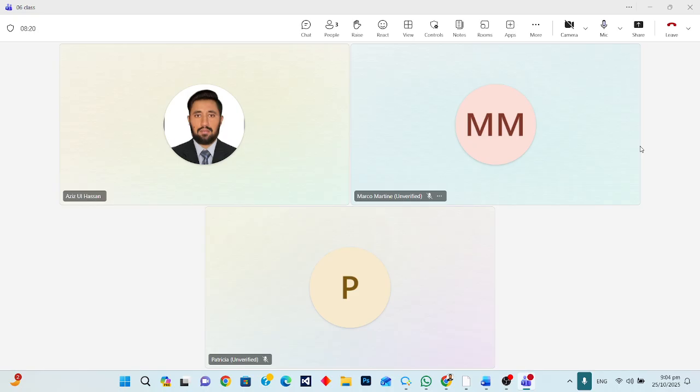For that calculation, we need to apply the classes of the LPS protection through the rolling sphere method in the PV area. So when we perform this risk assessment as per the IEC standard and the lightning protection as per IEC standard 62305-2, we need to roll our rolling sphere on the PV area.